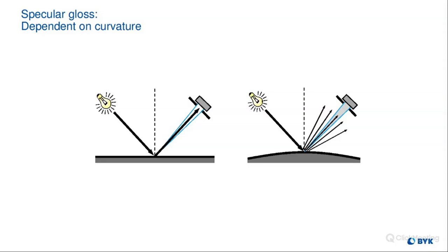An example of that would be if I wanted between a 50 and 60% gloss value for some type of part I was making, but it was curved. What I could do is create a jig so that the gloss meter is in the same spot every time on the part. I can take my measurements, and I may not get 50 or 60% gloss.